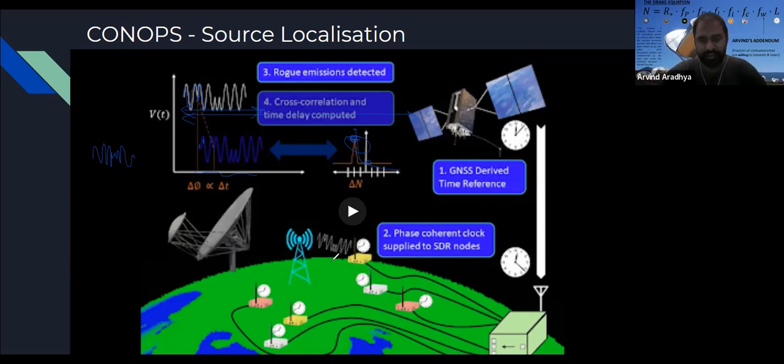Yes, Wi-Fi, and it depends entirely on the frequency that they're monitoring. At HCRO, at the telescope site, the antennas and everything are dealing with frequencies from a few hundred megahertz to about 12 gigahertz. Your Wi-Fi is at 2.4 gigahertz, and another Wi-Fi band is at 5 gigahertz. So if they're conducting an observation in that frequency range, if they're looking at a certain region of the sky at 2.4 gigahertz, then yes, you have to turn Wi-Fi off. Otherwise, it'll just swamp it out.